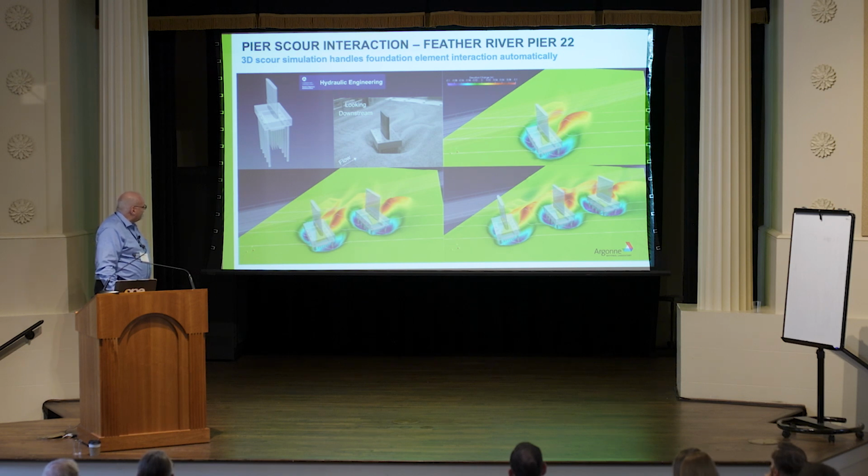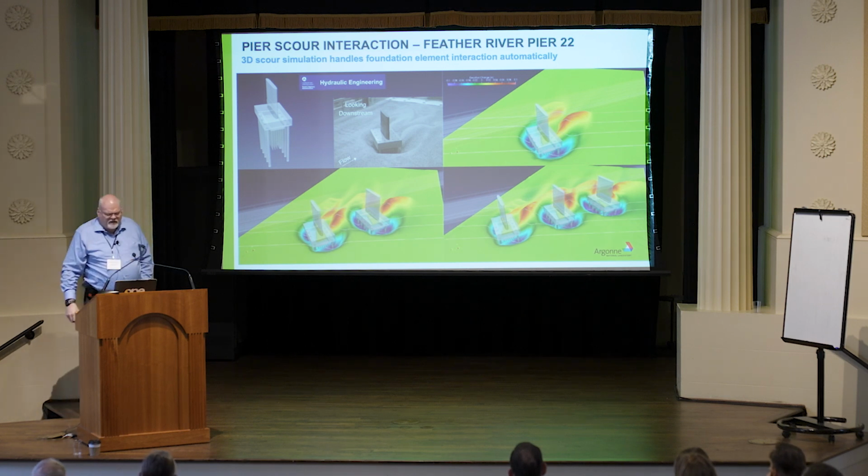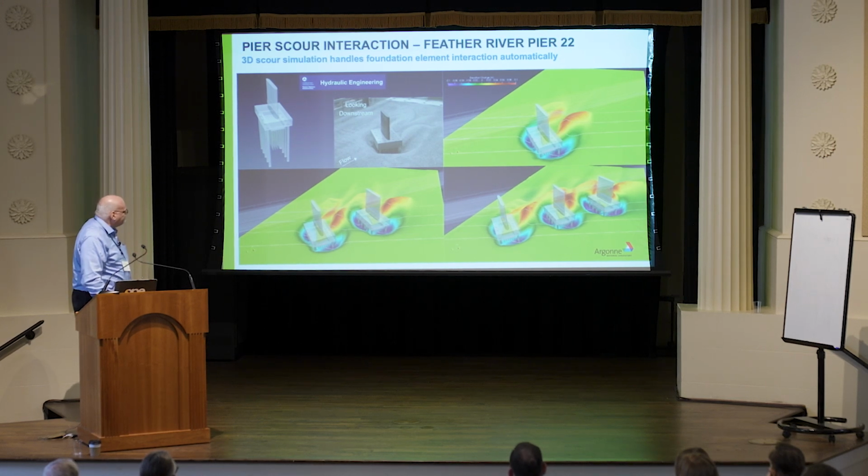You see a slight difference with regards to the formation of the scour holes. I mean, there are features on the hills that we're obviously not capturing perfectly. But then again, we only care what happens in the scour hole. Building up a little hill behind the bridge pier is not the most important thing. But I was surprised myself how well this actually works.